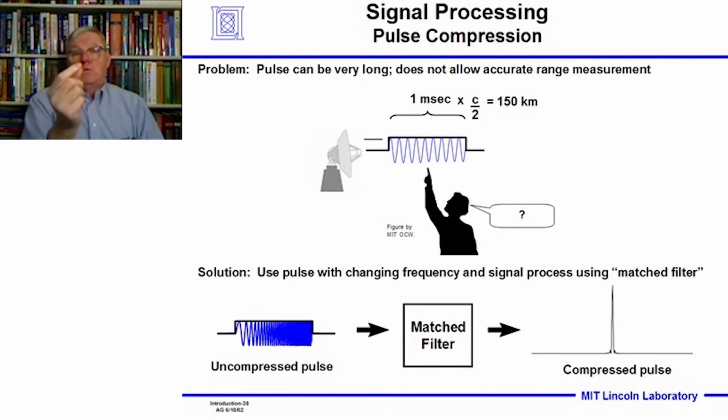If the target is much smaller than the pulse, you can't tell the range any better than the resolution of your instrument to measure it, which is the pulse width of the transmitted pulse. So if you increase the pulse length, you can get more energy on the target, but you lose in range resolution. But you want both. Is there something you can do?